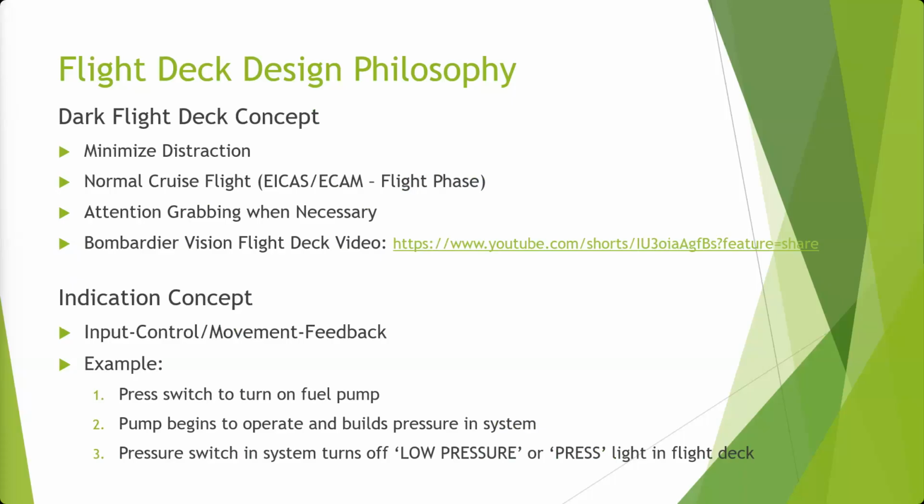What that means is that with everything dark and quiet and calm, when something becomes abnormal and a message pops up, or a light lights up, or some kind of an alarm or alert sounds, or a haptic item occurs, which is feel, think of stick shakers or pushers or other things like that that provide some feel, that grabs the attention of the person operating the aircraft, the crew member. Or on the ground, it could be you as maintenance personnel.